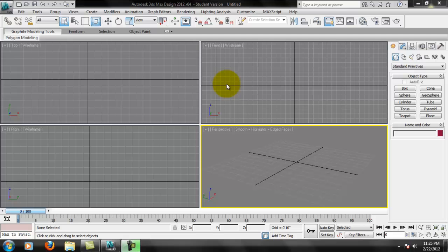Okay, so as I said before, everything that we need to really worry about in 3D Studio Max, for the most part, is going to be right over here. And it's organized in a hierarchy that will allow you to step through these pretty easily. So you can see here we have a tab, that's the new tab. Okay, this is the Create tab. It doesn't want to show the tooltip, but this is the Create tab here.